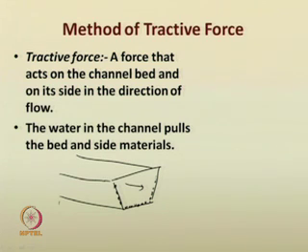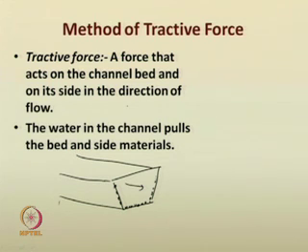If this force is too much, you can imagine these particles start coming out from the bed as well as from the sides. This force is called tractive force: a force that acts on the channel bed and on its sides in the direction of flow. The water in the channel pulls the bed and the side materials in the direction of flow. That is the property of the tractive force.